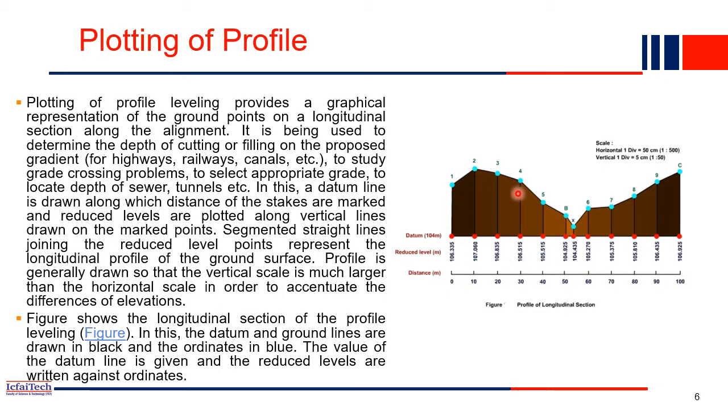So this is the profile plotting you can see. Now you understand how the profile exactly looks like. The different measurements you have taken, and all the height and rise and fall values, you will plot on a graph or a plane, and then you see exactly how the profile looks like. So this profile is very much useful for understanding before construction.